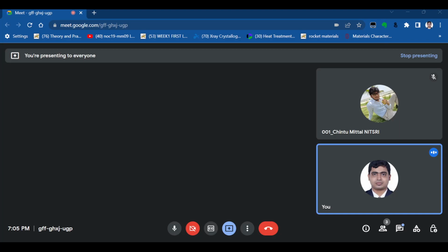Similarly, this is our sigma yy value, and we look at this point, which is sigma yy and tau xy. We draw a straight line between them, then we take this half length as the radius and draw this whole circle. So this is a Mohr circle. Wherever this circle cuts the x-axis, that is our principal stress, this one here and this one here.